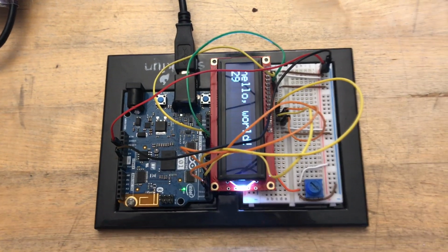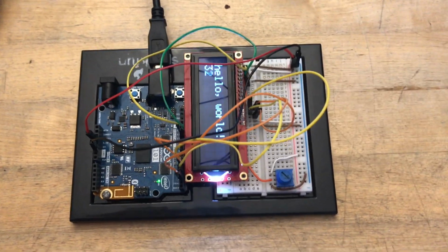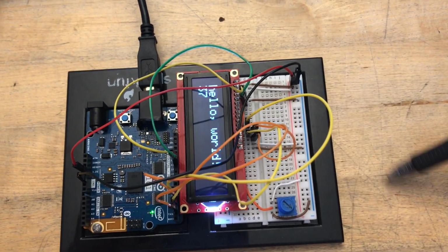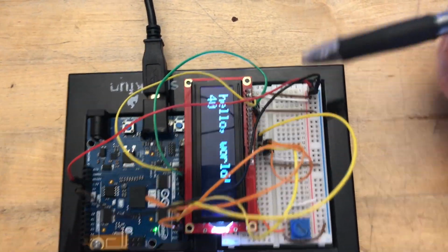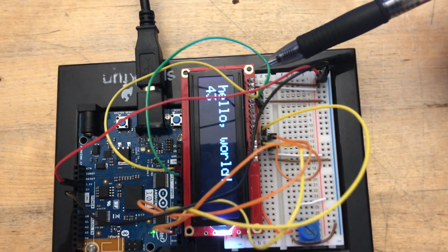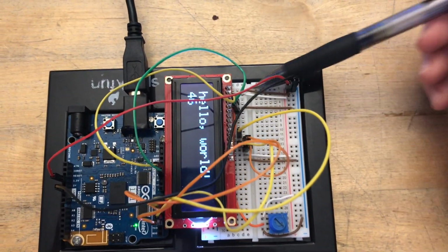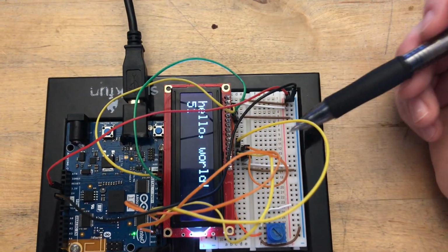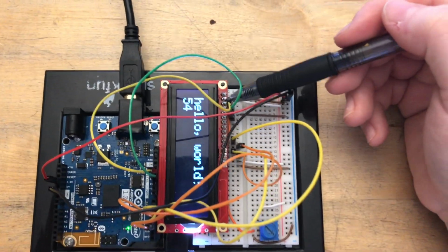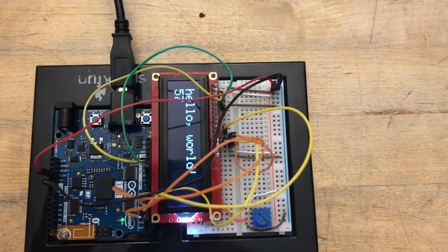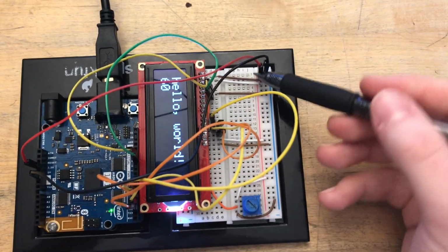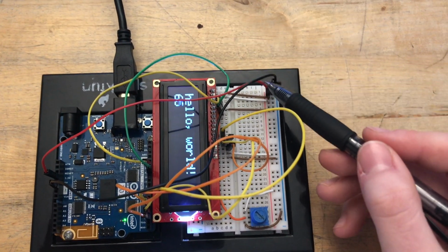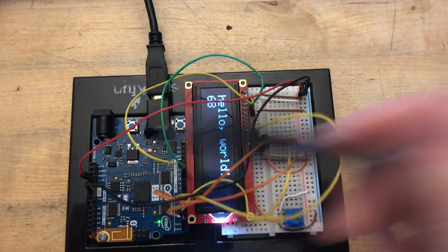Here's the basic board setup for using the LCD. Here we have the LCD screen, and there are 16 input pins here. The first pin right here is going to connect to ground, using this black wire, and the symbol for that pin is VSS. The next pin has the symbol VDD, and it's a power supply input for the driver IC, and that's going to connect through this white wire here and this red wire to the 3.3 volts on the board over here.